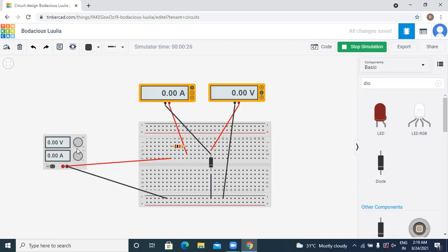Clear? Okay, sir. Take a notebook. Three columns will be there. One is the power voltage, the voltage that will apply in the power source. Then the ammeter reading and the voltmeter reading. So you take 5 readings. First reading 0 volt. Now you take say 1 volt or 2 volt. Place it somewhere as you like. Yes, 2.60. Anywhere you can place, no problem.